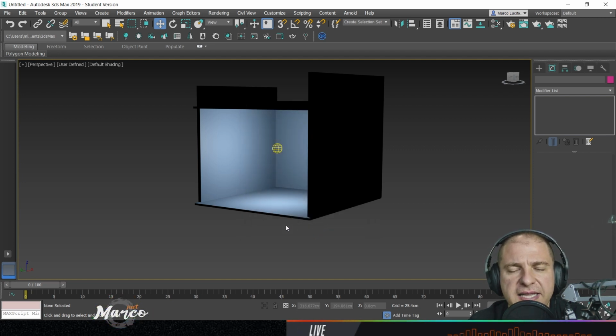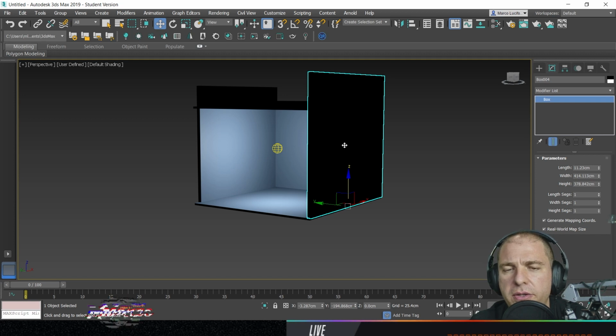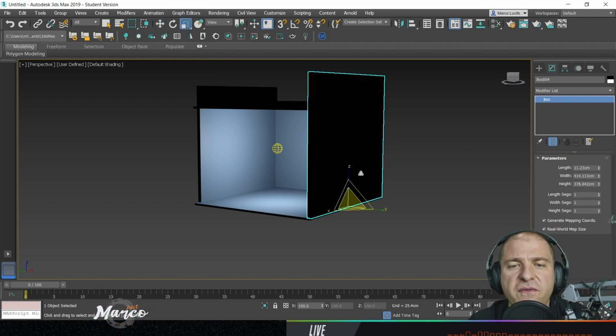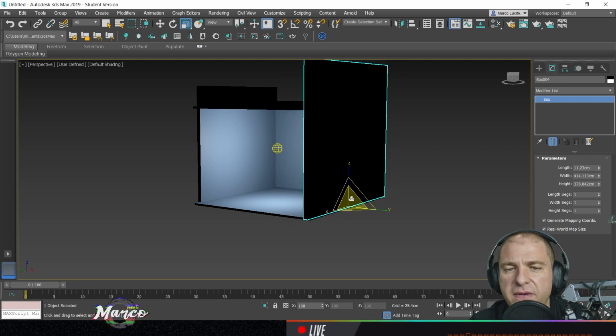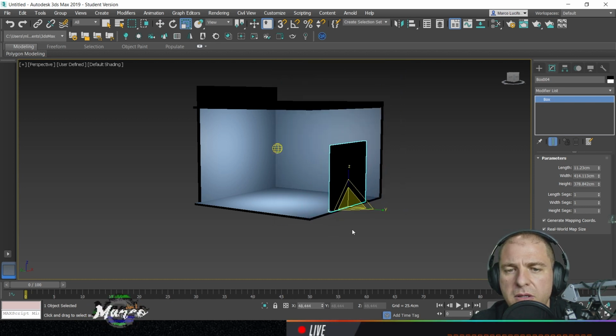This is first, and then if I want to check if the dimensions of my projects are fine, I do not have to rely on selecting the object and going to the Modify tab and reading these dimensions, because these are parameters. And if I scale my object, dimensions won't change. But what changes at the end is the final real dimension that I can instead easily measure by selecting the object or multiple objects at the same time.